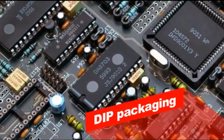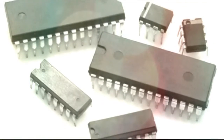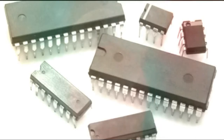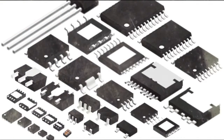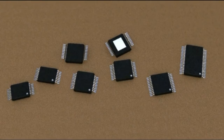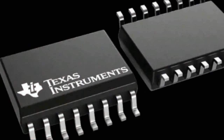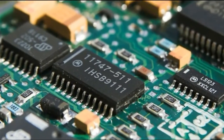DIP packaging, dual inline package. This type of packaging has two rows of bases located on both sides of the IC. This package is one of the oldest and most famous IC packages. SMD packaging, surface mount device. In this type of packaging, IC bases are connected to the board surface and the IC is placed directly on the board surface. SMD packages are usually smaller in size and are widely used in the electronics industry.